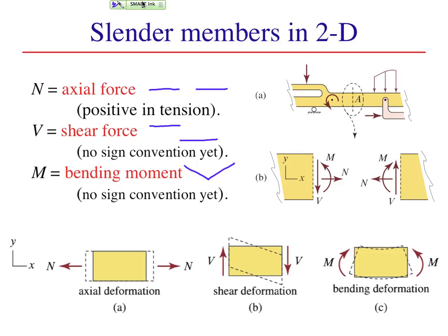Likewise, in 3D, we have 3 forces and 3 moments at the cut plane. There is no difference in the number and character of loads at an internal cut than there is at a built-in support on a full rigid body. In one case, the built-in support, the degrees of freedom prevented or impeded are absolute. In the other case, the internal cut, the degrees of freedom prevented or impeded are relative. In both cases, we have a full complement of loads.